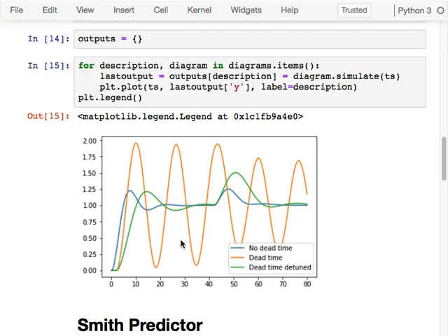Now, that's the simulation version of this. Yesterday, when I was incorporating some of this frequency domain reasoning about why these controllers work, I felt that I was losing a couple of you. I could feel the eyes glaze over as I was doing that. So I want to talk about this degradation in control performance from a frequency domain point of view. I feel that understanding the frequency response of these systems gives you some explanatory insight into why dead time does this.